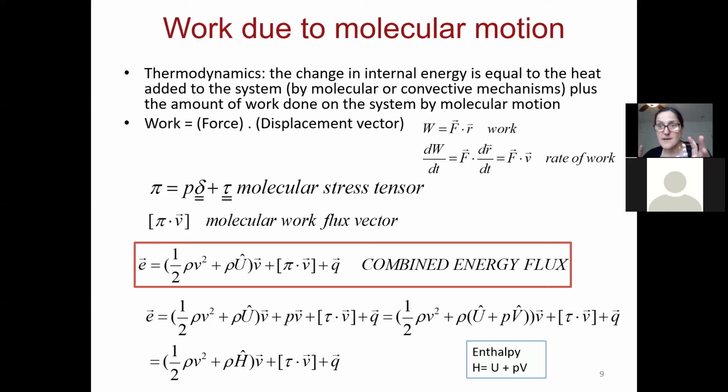In essence, our Navier-Stokes equation, however complicated looking, is Newton's law: F equals mass times acceleration. It's just that quantifying all of those things in the presence of different fluid layers moving is complex. That's why we actually needed these stress tensors. So I don't have just simple force dot V. That's what I'd love to do for some area, but I can't do that.